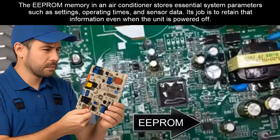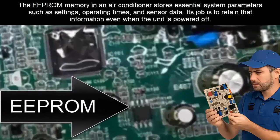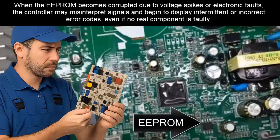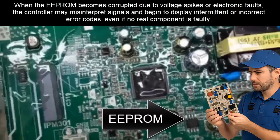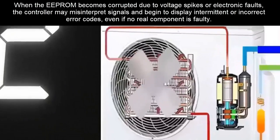The EEPROM memory in an air conditioner stores essential system parameters such as settings, operating times, and sensor data. Its job is to retain that information even when the unit is powered off. When the EEPROM becomes corrupted due to voltage spikes or electronic faults, the controller may misinterpret signals and begin to display intermittent or incorrect error codes, even if no real component is faulty.